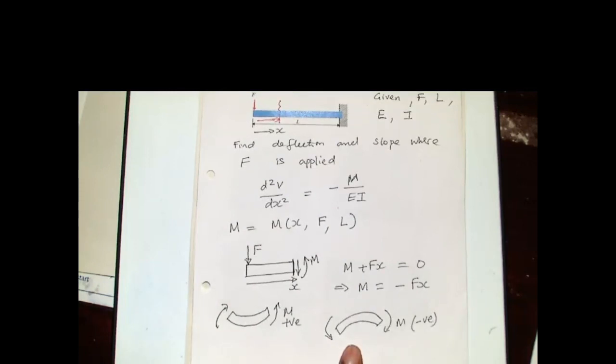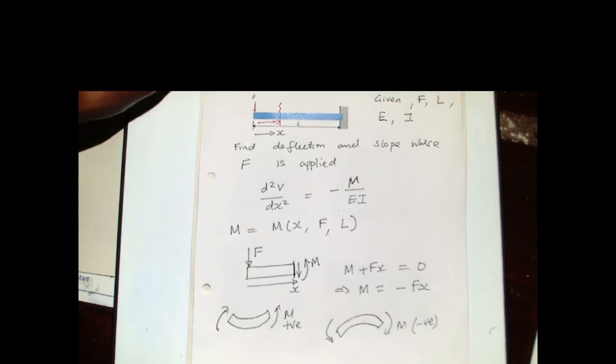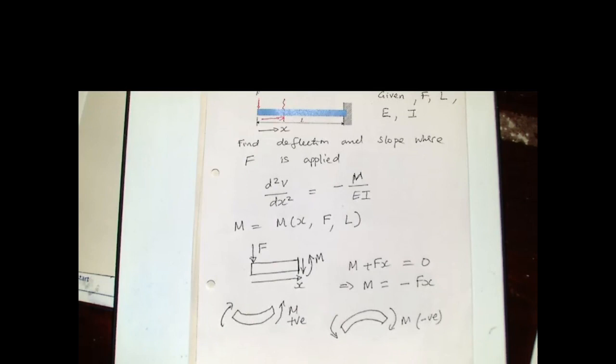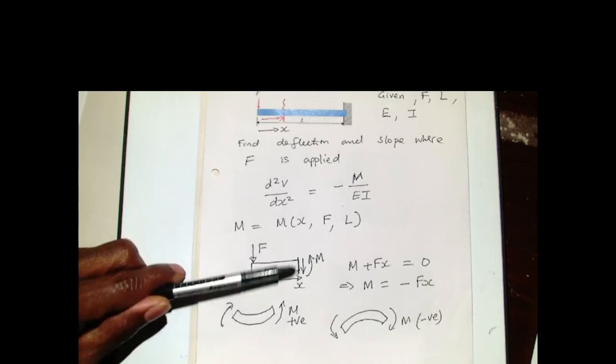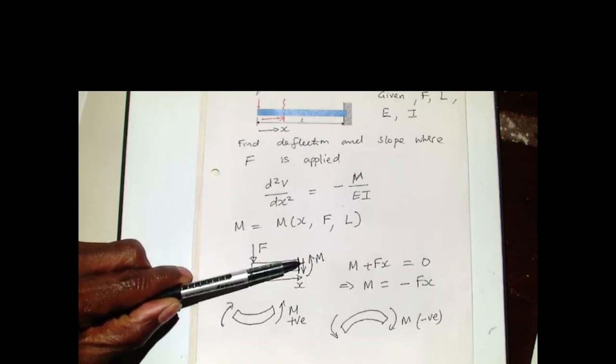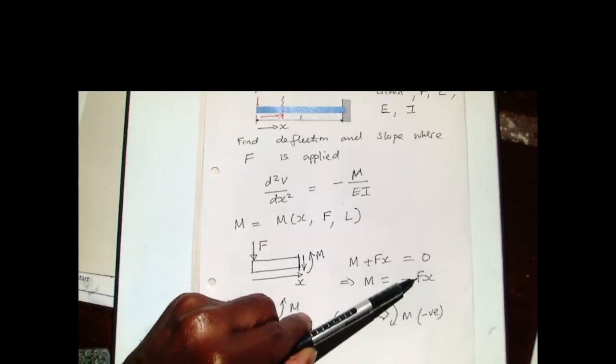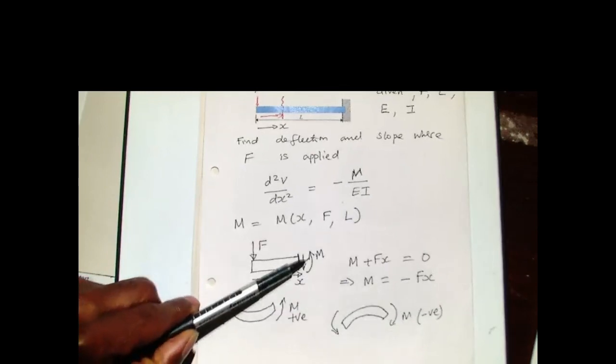But see, the drawing in the middle, you've got M and the anti-clockwise arrow, and your answer is negative. So we know that the direction we assumed was wrong. If the answer was positive, we would know the direction is positive. So this direction I've chosen as giving me this. But because I'm getting a negative number, it means that this moment here is actually acting in the opposite direction.